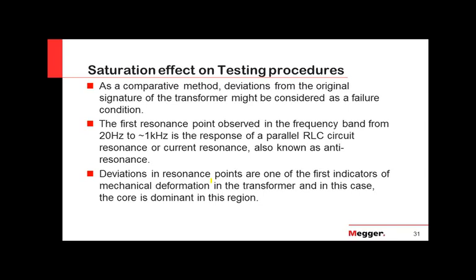Every time you're doing an SFRA test, be careful obtaining your first or your maxima on your resonances, and all the information has to be available for you. If you are acquiring a transformer, if you're buying it from a manufacturer, please request the information to be electronic, okay?